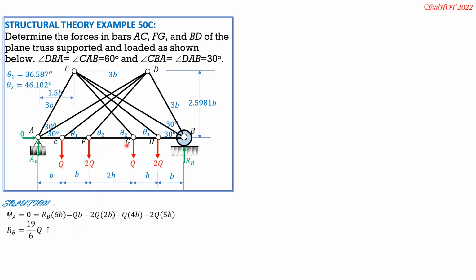Then we begin with joint G to solve for F_CG, and we proceed to H to solve for F_CH. Then knowing these two forces here, we isolate joint C as a free body diagram because we want F_AC and F_BC. Take note, F_AC and F_BC are perpendicular or 90 degrees at C. So these are the forces involved at joint G. This is required, so that's why it's red.